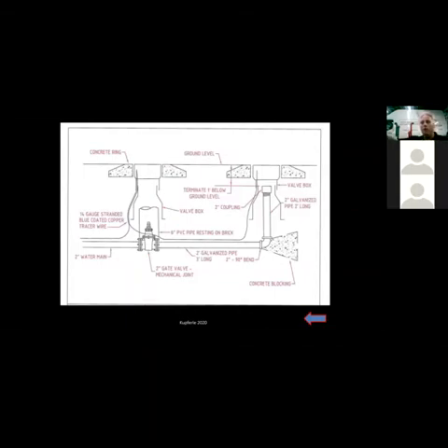So I can replace them all right away, or I can put in my spec, and anytime this gate valve goes bad, I don't even have to put the gate valve back in. I can just put the TF500 at the end here, and if there's another shutoff up the line, I can use that other shutoff to turn off the water to do maintenance. If there's not, you need to replace your operating mechanism. But if there is another connection up the line where I can turn it off, you can just skip putting that gate valve or that curb stop or that ball valve altogether once again.